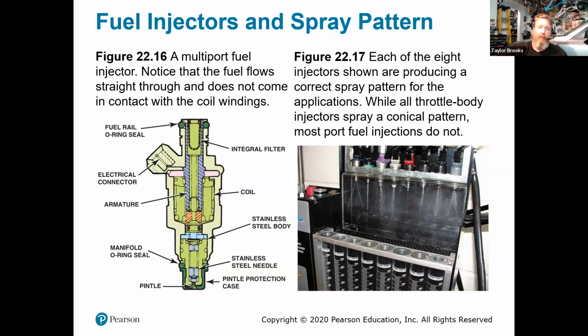I do want to make sure it's understood with this design that the electronic solenoid component of the fuel injector is completely separate. The fuel is going to be passing straight through a port that is only blocked off by the pintle and the needle. When we have this type of system, it's very rare for fuel to come in contact with the coil. In fact, I've never heard of one. That being said, knock on wood, it's bound to happen at some point. But the system is pretty simple with how these injectors work.